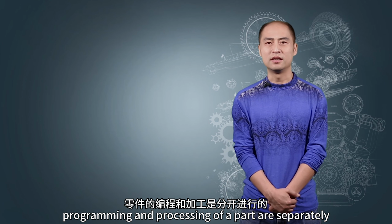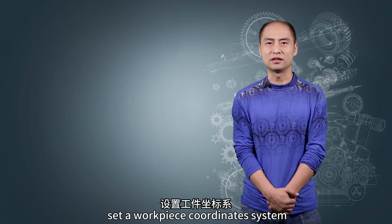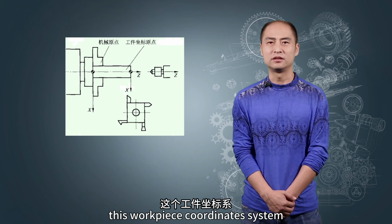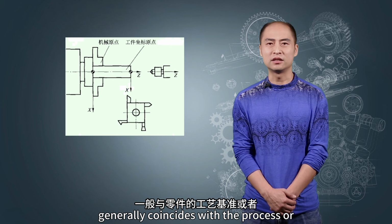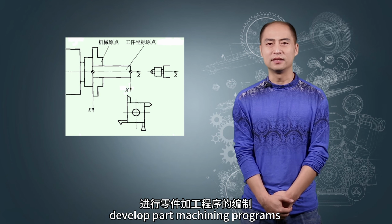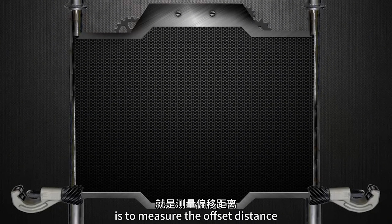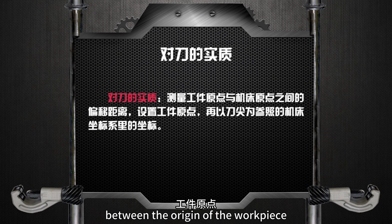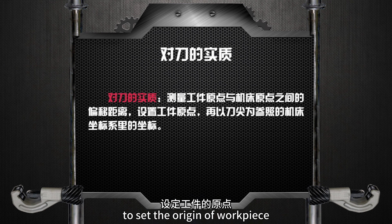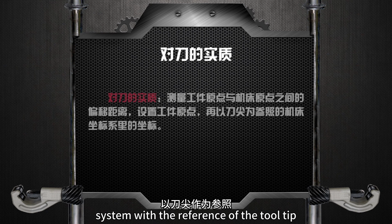Generally, programming and processing of a part are operated separately. Programmers set a workpiece coordinate system convenient for their work according to the design drawing. This workpiece coordinate system generally coincides with the process or design reference of the part. Develop part machining programs in the workpiece coordinate system. The essence of tool alignment is to measure the offset distance between the origin of the workpiece and the origin of the machine tool, to set the origin of the workpiece and the coordinates of the machine tool coordinate system with the reference of the tool tip.